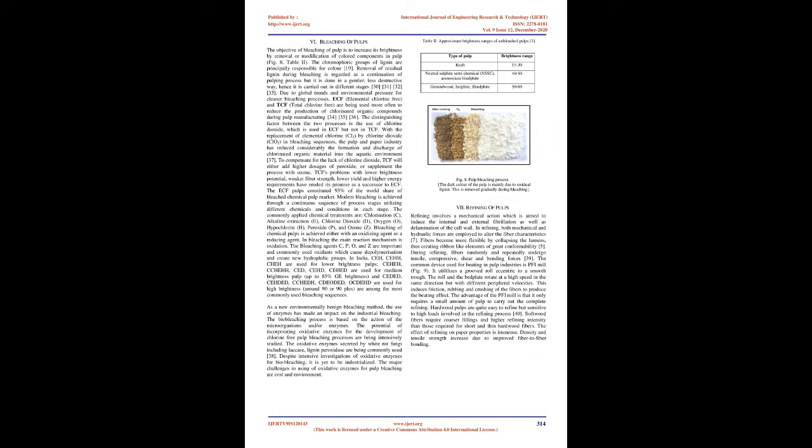27. In the bulk phase the cooking temperature accelerates the reactivity and leads to depolymerization of lignin. The rate of lignin dissolution remains high and about 85 to 90% of the total lignin, from secondary cell wall layers, is removed. 28. The slow residual delignification phase is related to the removal of condensed lignin units and is affected by the alkali charge and the cooking temperature.